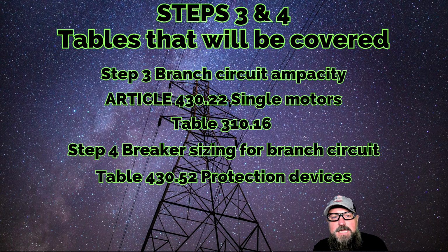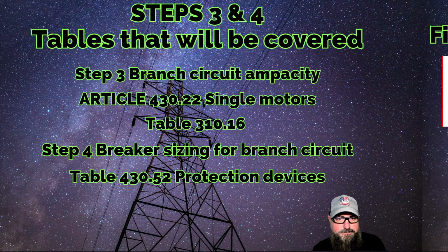Step 3 and 4, the tables that we will be covering. Step 3, branch circuit ampacity: Article 430.22 for single motors. You'll also need table 310.16. Step 4, breaker sizing in branch circuits: Table 430.52, protection devices. So make sure you're ready to use those tables and let's move forward.